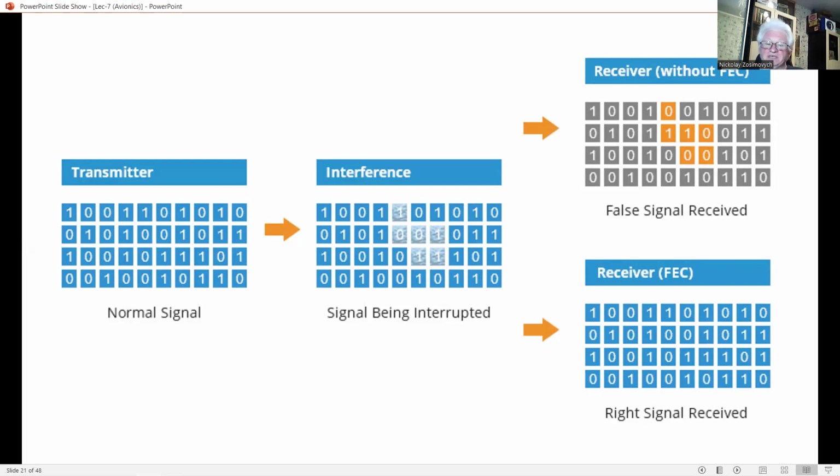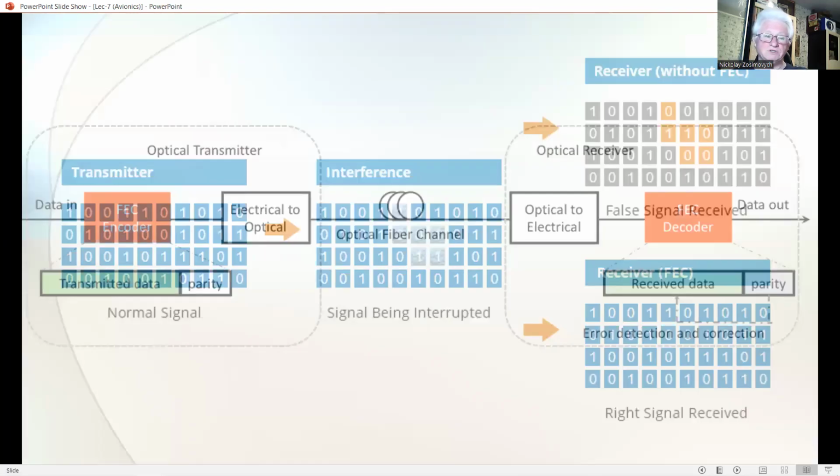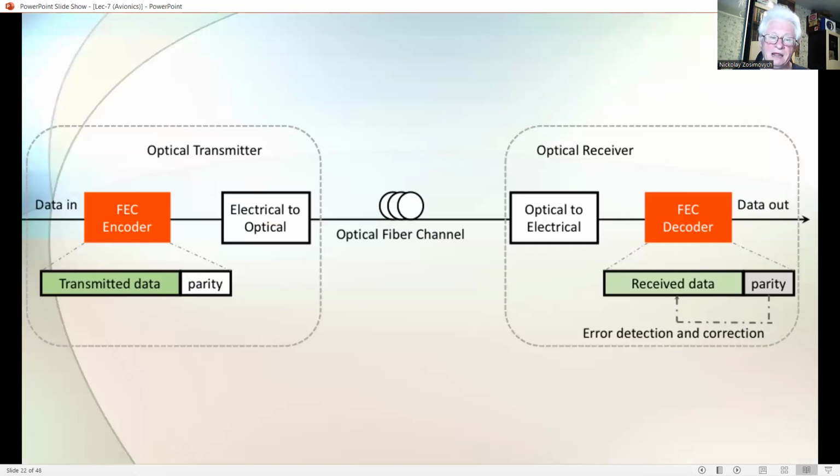The integrity of the screening of the interconnecting cable must thus be very high indeed to meet the flight safety requirements. The use of optical data transmission, whereby digital or analog data is transmitted as a modulated light intensity signal along a fiber optic cable, overcomes this problem.